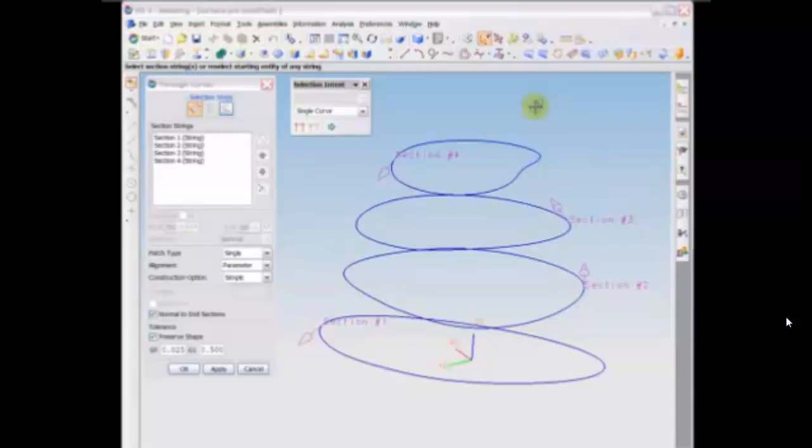Finally, one common problem often comes about when using closed curves to create ruled surfaces or surfaces through curves. When using a circle or closed spline as a profile, it is not always easy to control where the start and end point of the profile is placed. Thus, when you select your profiles, although the curves may be chosen to progress in the same direction, either clockwise or counterclockwise, their start and end points do not line up. This will create a twisted surface.